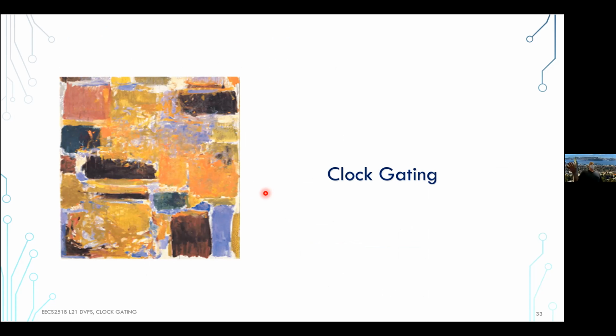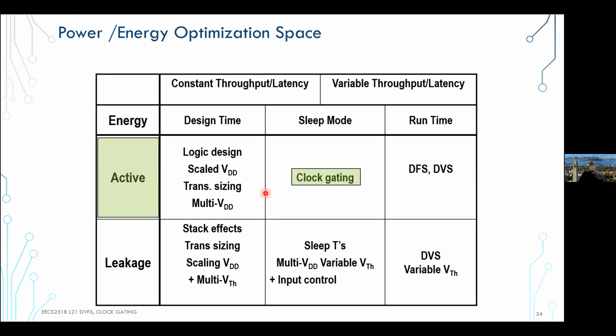So that's just a really fast intro into the world of DVFS and all the issues. We're going to talk a little bit about clock gating. This is a very frequently done optimization now, actually also by a lot of EDA tools, so you don't have to worry about it. But it's often a good thing to check what the tool has done, because the tool often doesn't do the smartest thing, and depending on your design, you may need to go and explicitly tell it the clock gating.